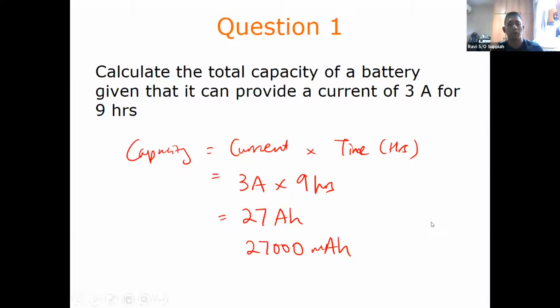That is basically how you define capacity. This is the amount of current that it can totally discharge. How fast it discharges and everything depends on how you connect up the circuit and the C rate at which you're operating. But this is the total capacity of the battery. So you just take current multiplied by time. It's a very straightforward calculation.